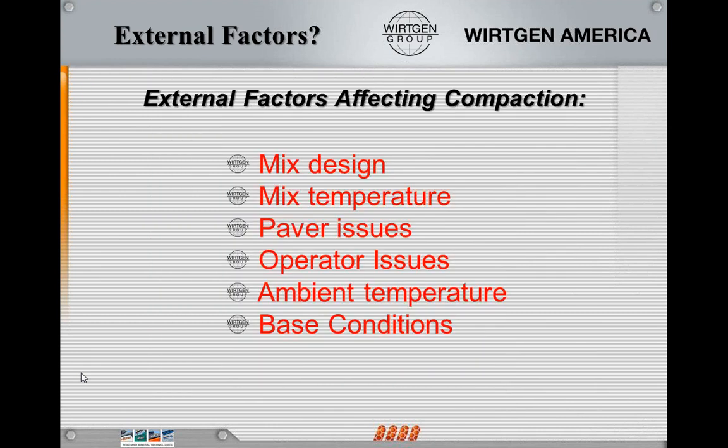But guess what? There are several different types of mix designs out there that change the way we try to compact. We have Superpave mixes, SMA mixes, polymer modified mixes, open graded friction courses, thin lifts, thick lifts. A lot of the designs, we're not going to be compacting the same way. So understanding and having the knowledge of what you've done in the past helps you get through and get better compaction and better density.